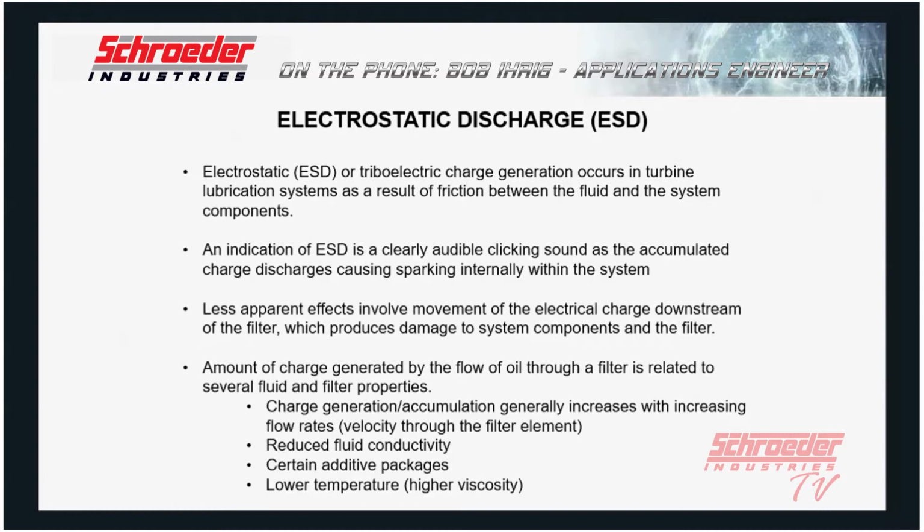But an indicator of ESD, without actually seeing the fluid itself as it's being cycled through a system, is an audible clicking noise coming from a reservoir or from the system. It doesn't sound quite like cavitation. There are distinct differences in the noise. And like I said, it's common to see it at a filter, or somewhere on a reservoir.